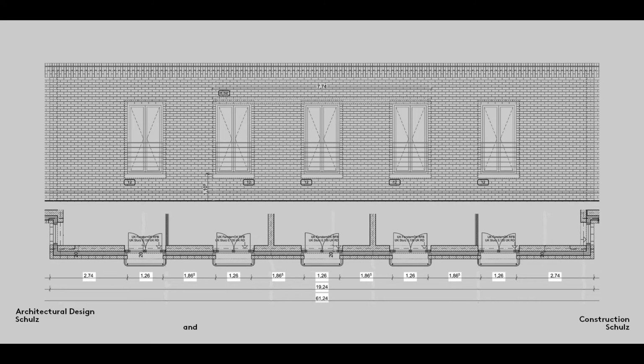Masonry construction drawings contain only these three types of dimension, and they are always shown in a certain relationship. In a dimension chain for window openings in an external wall, for example, the opening dimension of the window is always followed by the external dimension of the adjoining section of wall, and then the opening dimension of the next window. As a result, the addition of all the dimensions in a dimension chain must give a working dimension.